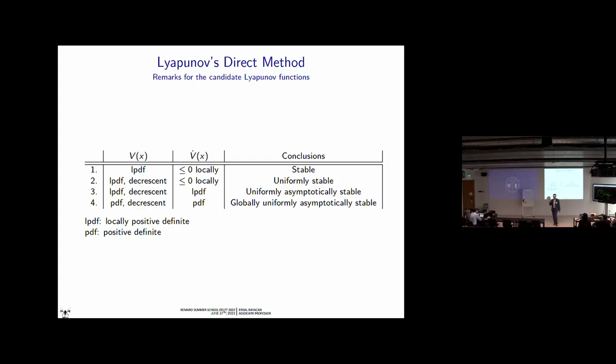You should say yes. Why? Because in any LTI system, your solution is, like in the first set of slides, c times e to the power of lambda t. So that means the solution is going to go to 0 with an exponential function. So linear systems, again, just a summary: if they are stable, they are globally stable, asymptotically stable, and exponentially stable.